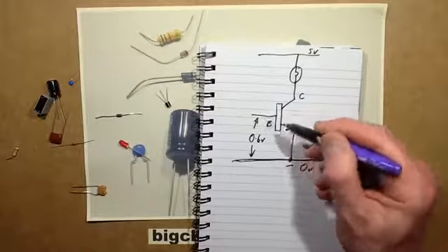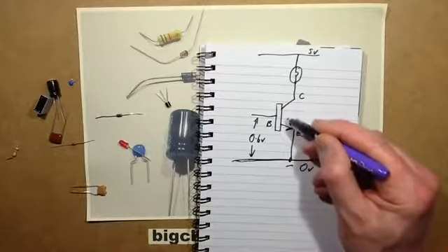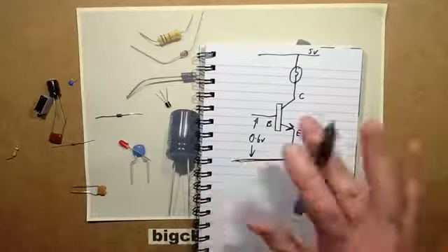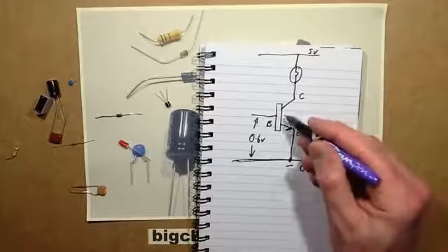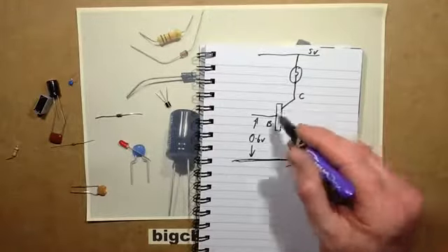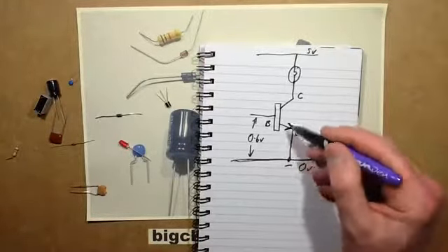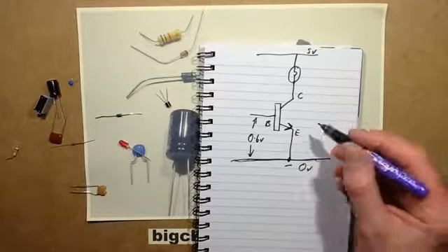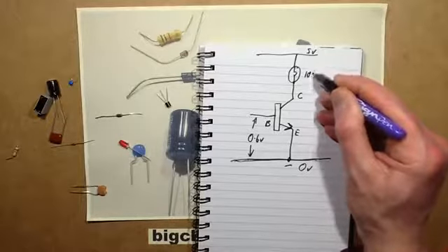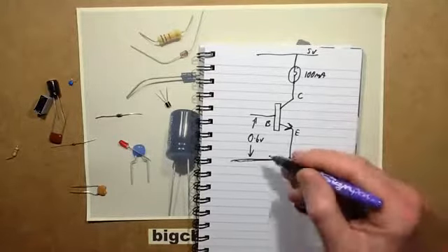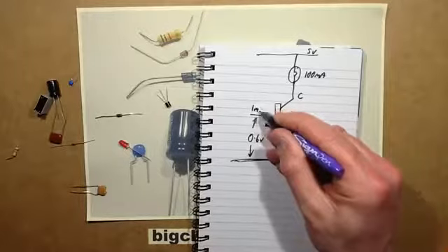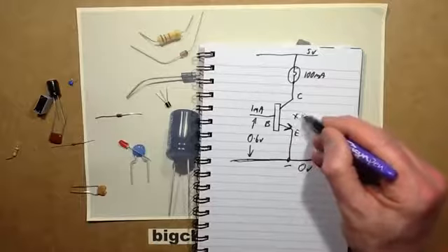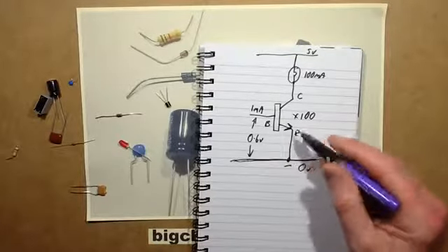a modest current, a transistor typically has a value called a gain. It's got a voltage rating, a gain rating, and a power dissipation rating. There are lots of other ratings, but let's keep it simple, because in most instances when you're using a transistor, it's going to be an NPN that's going to be like this. Say for instance, you've got a gain of 100, and that lamp's going to pass 100 milliamps to light fully. Then you want to pass at least 1 milliamp into the base here, and that will then be multiplied by the gain of the transistor, and it will switch the lamp.